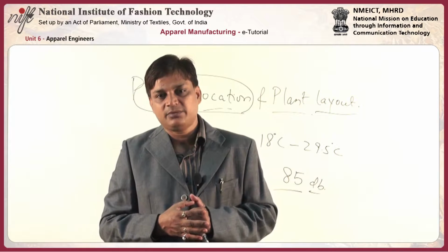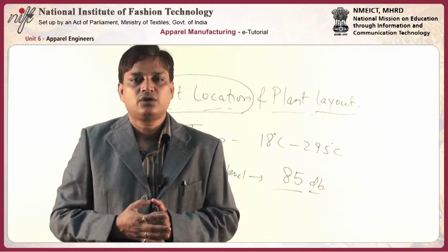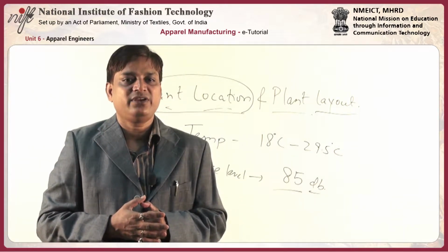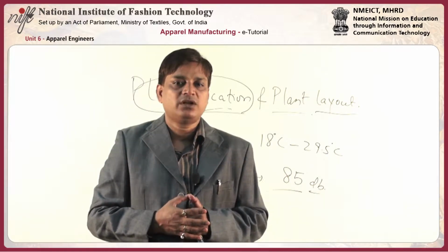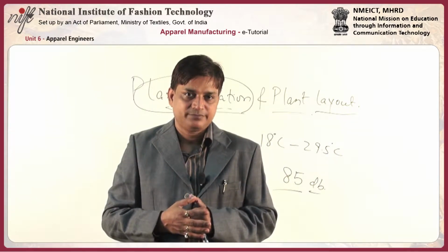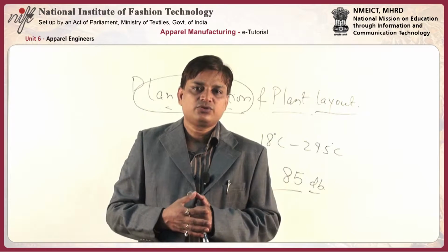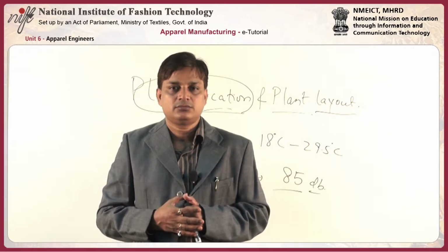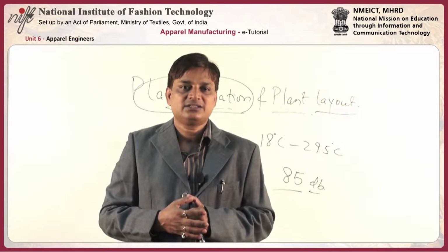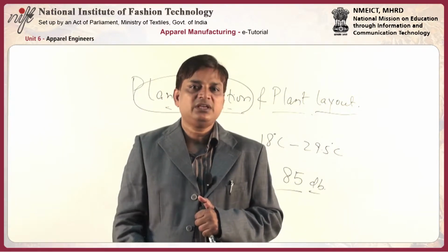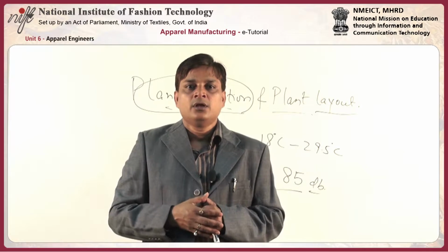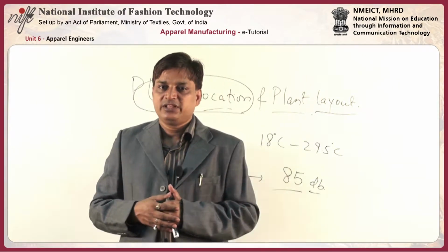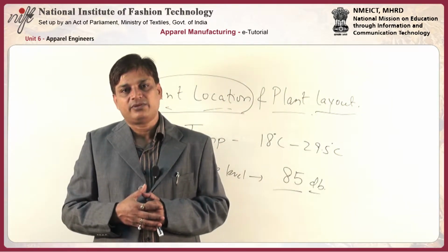Facility floor maximum travel distance should be 75 feet, or for a warehouse, 1 per 1000 square feet. Fire extinguishers are to be mounted on walls and columns, a maximum of 4 feet 6 inches, that is 1.5 meters, above the ground. So a fire extinguisher should be within 75 feet of any employee.